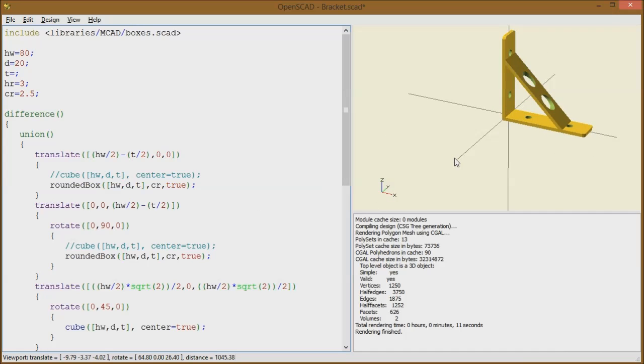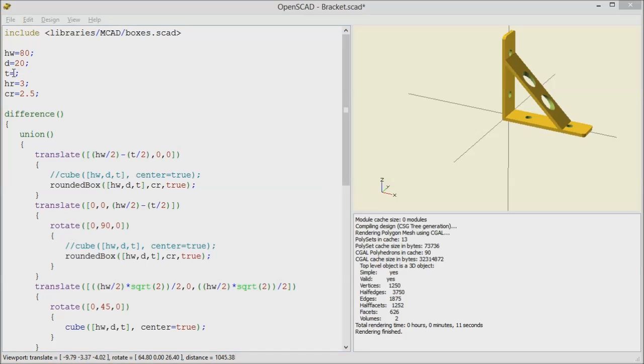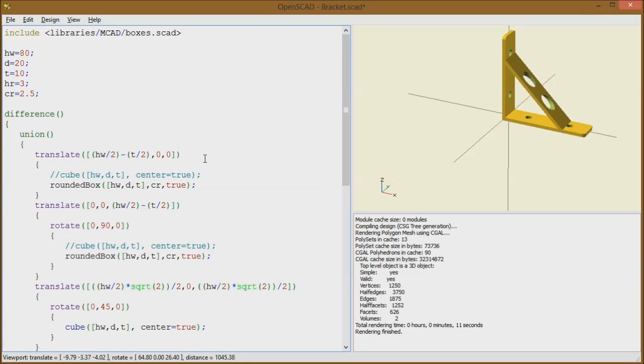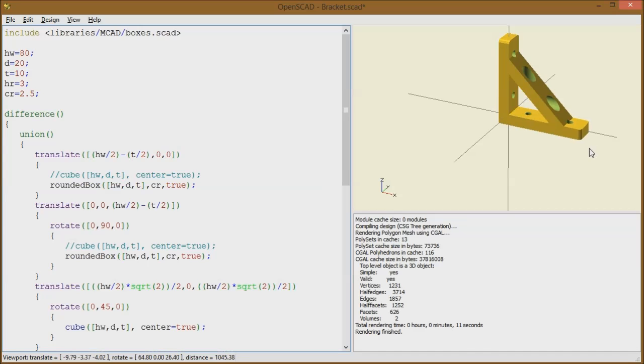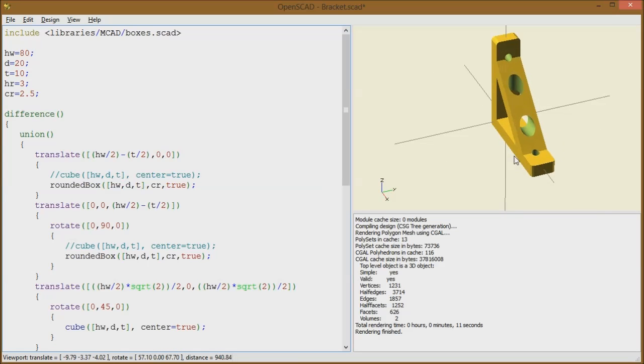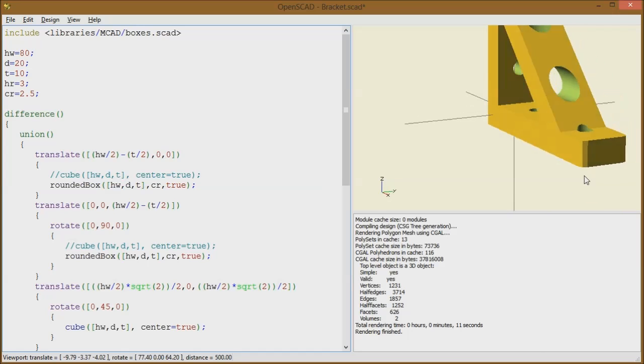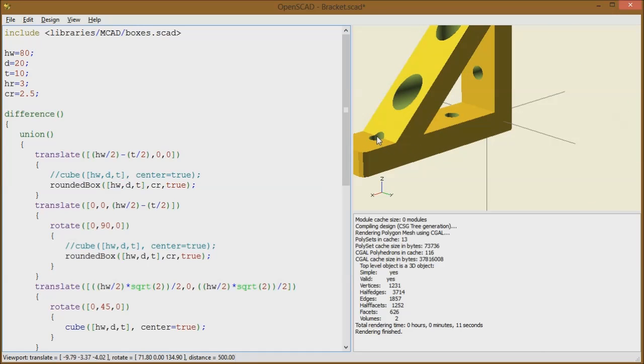If we look at this specific model of mine, if we made the thickness 10, I can spot a problem that we might have. Pressing F6, letting it build, you'll notice that our cutouts for our holes are not going to be deep enough. Actually, I think, no, we have taken care of that because we have specified that they have to be double the thickness.